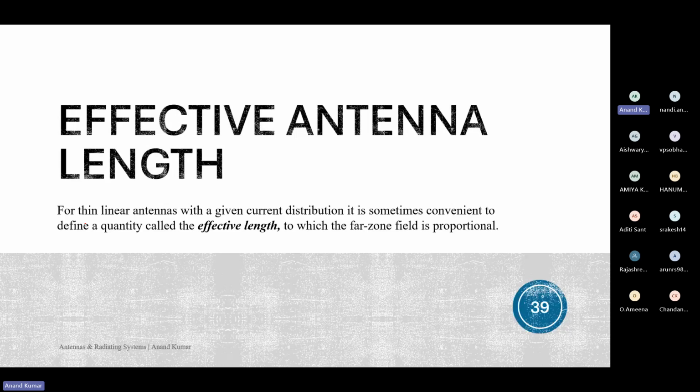Now within this topic, there is something called effective antenna length, which is very important to know. Even if you have an antenna of a particular length L, and you say we are working at a certain frequency, a certain wavelength lambda, it does not mean that every antenna of this length will always radiate at the same frequency.